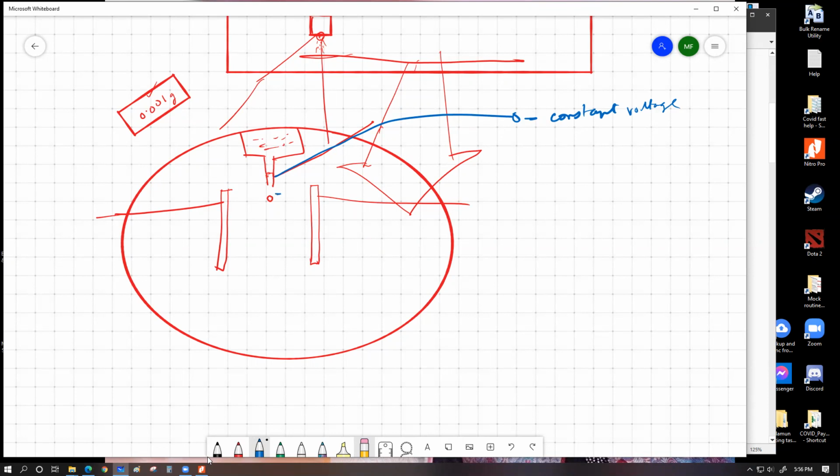Let's say one ink droplet comes out with minus, taking 10 electrons. Each of the ink droplets which come out of this hole are all going to take 10 electrons. So one thing we're trying to make sure, as the ink droplets come out of the nozzle, is that all of them have the same mass, or the same size. Shape is essentially circular, spherical. And also by keeping the voltage constant, we're making sure that all of them are charged by the exact same amount. You might wonder, why is that necessary? Why do we have to do that?